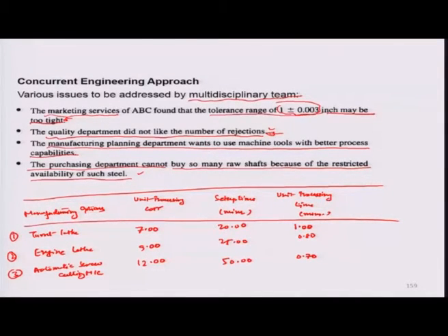The process standard deviation for all these machines are also given, while working on a mean size of about 1. So, you know that the desirable mean for all these machines is about 1 inch as given earlier, but the standard deviation of the processes are different. In the turret lathe case, for example, you already know that the sigma j happens to be about 0.003.